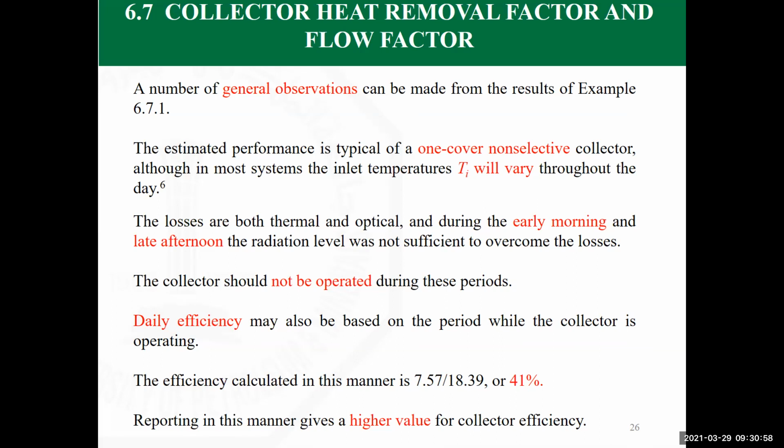Or the last hour of the sunset, I don't have to run it there, because the amount of solar energy which is coming in is small. It's not enough to take the load of heating the water, so there's no point of taking this in our calculations. If we exclude that from the table that you have, you are going to end up with a higher efficiency, because you would be eliminating the hours of low energy flux coming in.